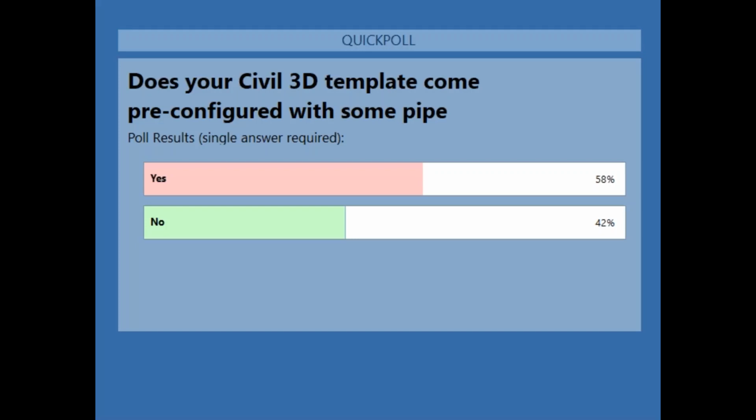You can attach more than one pay item to a pipe. Now you might think, well, why would I want to do that? 100 PVC and a 150 PVC? That makes no sense. No, that's not what you want to do, but that's what could happen. Typically, the reason I would attach more than one pay item to a single object is that pay items aren't just for calculating new materials.